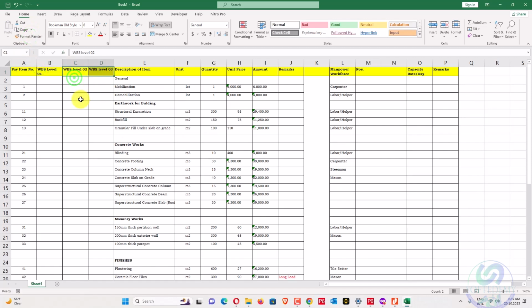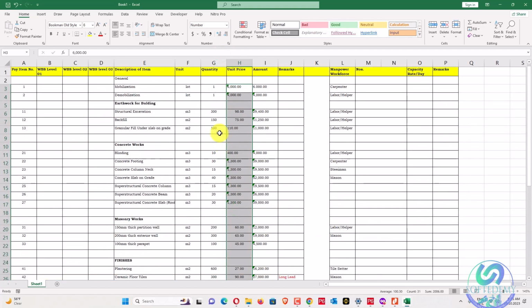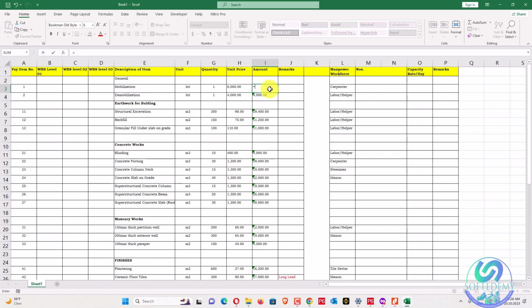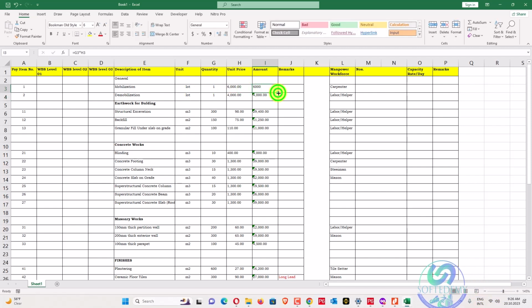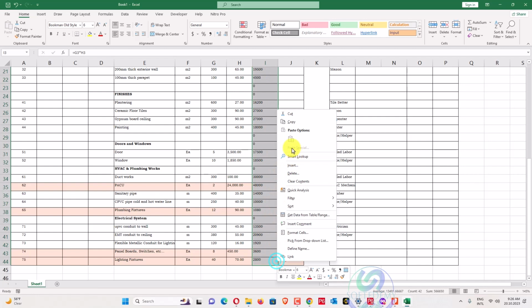So we have level 3, and now we have to just make sure that the prices are okay. We'll go here, next, numbers, prices, and now I will select all, and then convert to numbers. Here I will apply the formula: equal to quantity multiplied with the rate, and then I will drag down and copy that formula and paste until the end of the project.